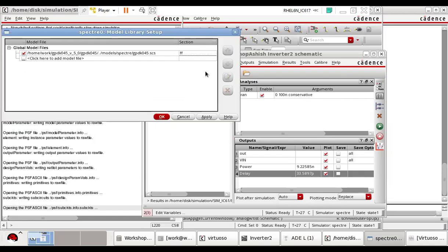What is the meaning of fast PMOS and NMOS? Fast means the threshold voltage is low in this case. When threshold voltage is low, there will be higher current. See, process corner means in extreme conditions, how fast your NMOS can be and how fast your PMOS can be. It is about the saturation current of the highest value.